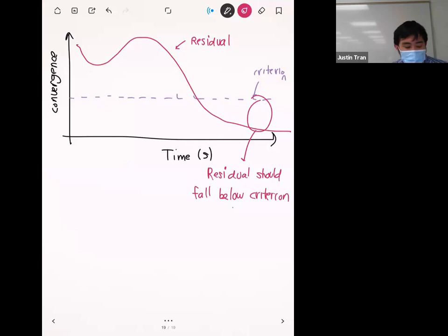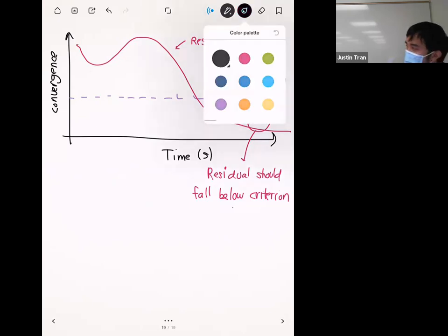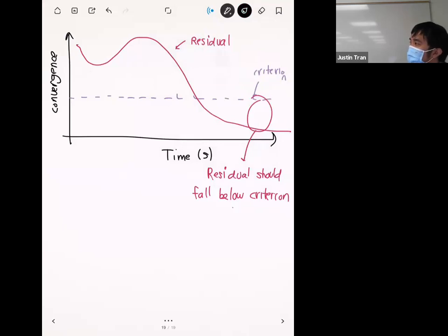The word convergence and the word converge is used a lot in finite elements, and unfortunately, it's used for different things. But for this case, what we say is that the nonlinear parts of your simulation are converged. And so I try not to use that word, just because we already have mesh convergence, which is another concept, and honestly, I think the more important concept. But when you do check these plots within ANSYS, that's the terminology that they use. So convergence is good, and in general, you want your simulation to be converged across many different places, and this is just another place where you can check convergence.